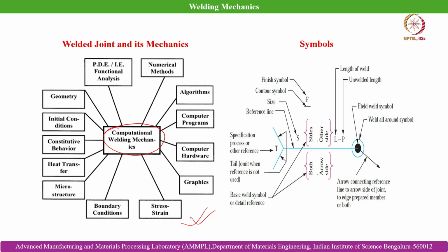Now when we discuss the design of the weld joint, it is important to learn these symbols. This is the symbol which shows weld all around. This circle signifies that you have to assume that there is a circular body which is getting connected over a plate. So, the weld all around symbol signifies that you have to weld it throughout its periphery. This is a kind of symbol which signifies to the manufacturer its applicability for the joint development. This is how the joint is developed.